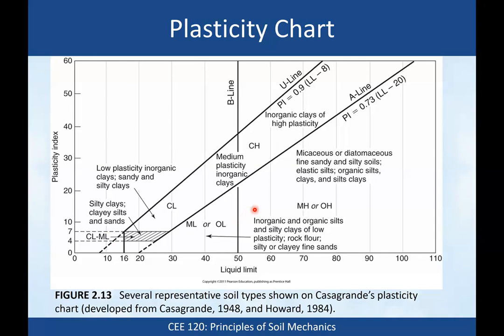The best way for you to present your Atterberg limits results is to put a point on this chart. So there are equations for these lines. It's easy for you to reproduce them, draw lines using Excel or something like that. Plot your point on the chart and print it and put it in your report. That will show your client exactly where your point lies, just like where I left the little red data point there, with the laser pointer. It's a good way to present that result.